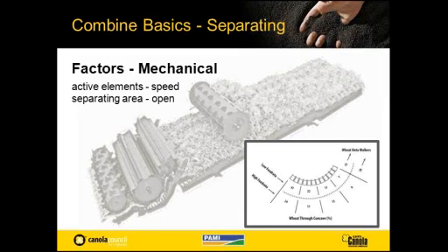And so we look down and see a typical separation pattern from a concave, and you can see that in the first few bars, a huge amount of separation takes place. If we were to take, say, the first 4 or 5, almost 50% of the grain at a lower feed rate will fall through in that front section.